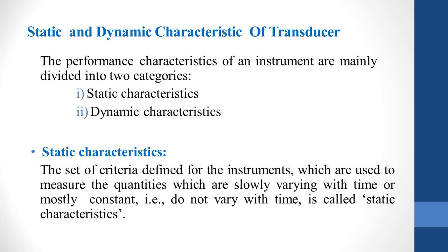However, many measurements are concerned with rapidly varying quantities, and therefore, for such cases, we must examine the dynamic relation which exists between the output and the input. This is normally done with the help of differential equations. Performance criteria based upon dynamic relations constitute the dynamic characteristics.